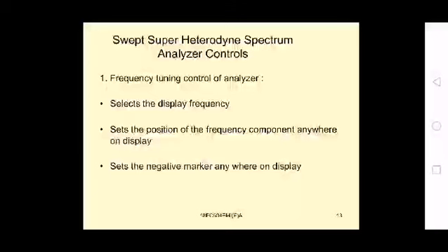So the swept super heterodyne spectrum analyzer controls: mainly frequency tuning control of the analyzer and selecting of the display frequency. This sets the position of the frequency component anywhere on the display and sets the marker anywhere on the display.